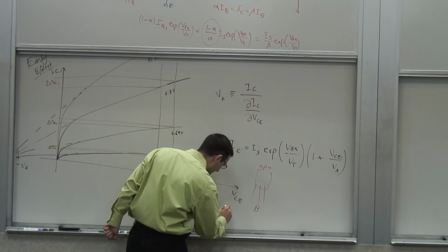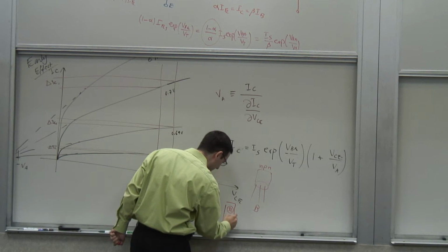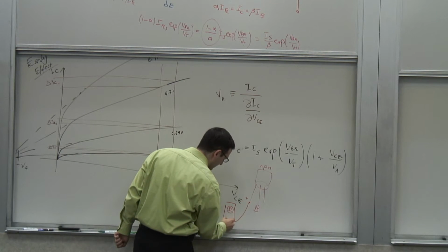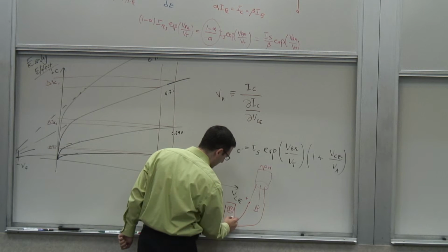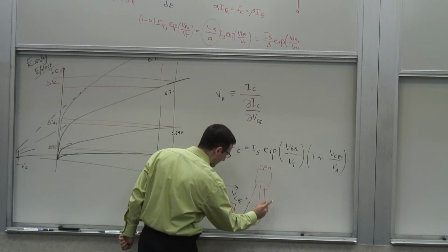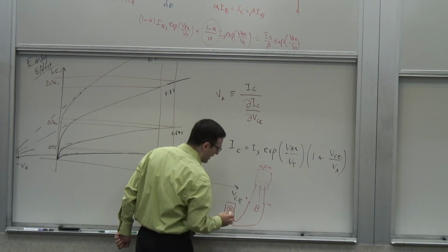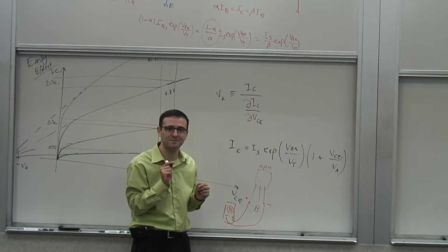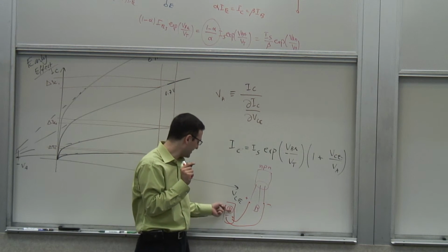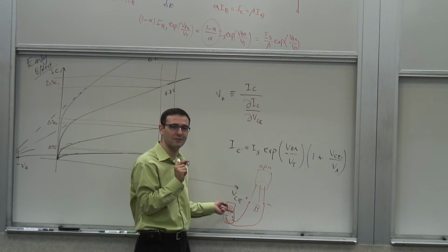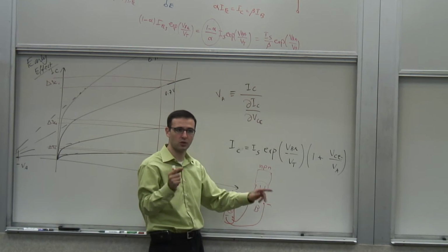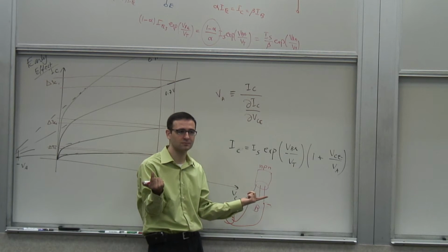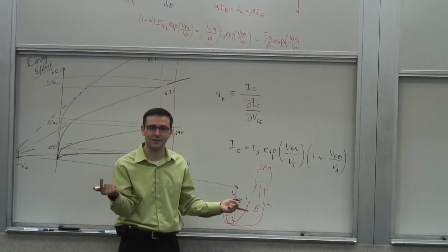I take my ohmmeter and connect the positive to one of the terminals and the negative to the other terminal. So this is the positive, this is the negative one. And I touch the base with the tip of my finger. Initially the resistance is infinite, because you are looking at 2 back-to-back diodes. No discernible current will flow.